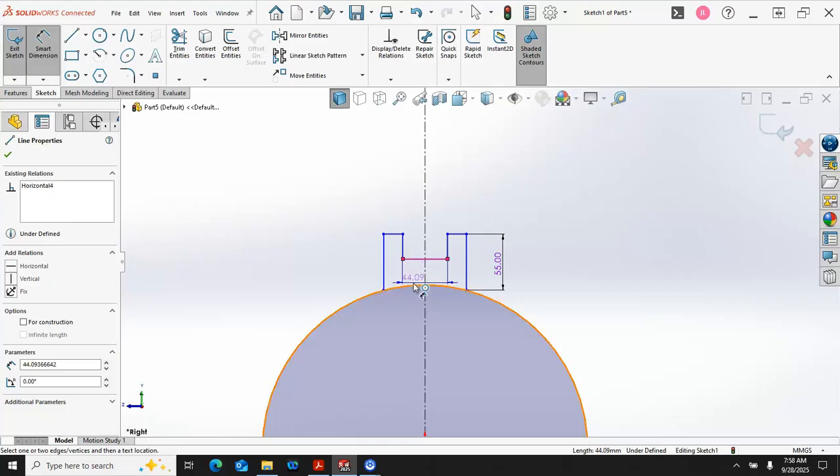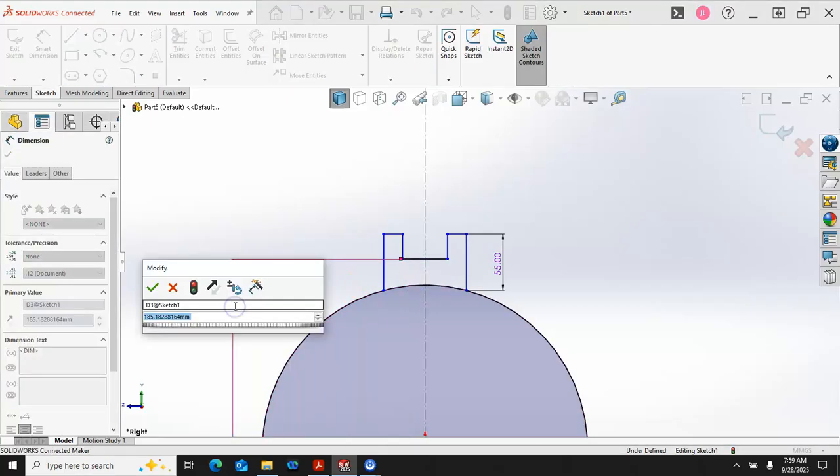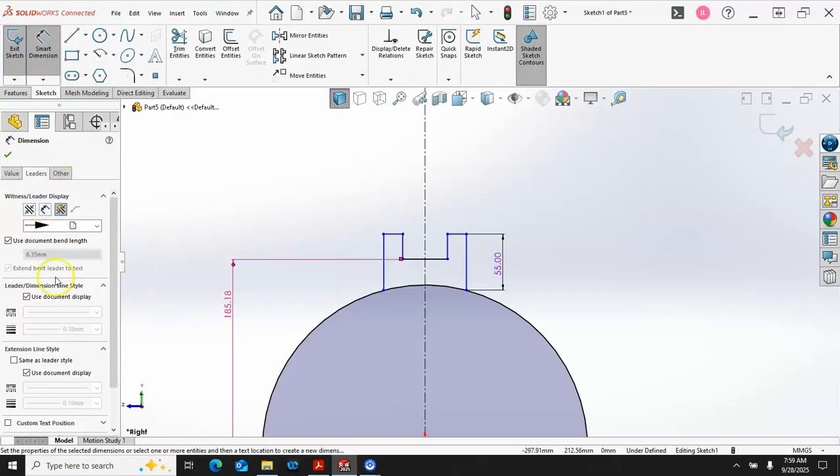And let's go ahead and hold down the shift, and I'll show you the difference. The shift gives us that min condition going to the arc, as opposed to picking the circumference without holding down the shift. We're going to accept whatever it gives us just to clear it out.